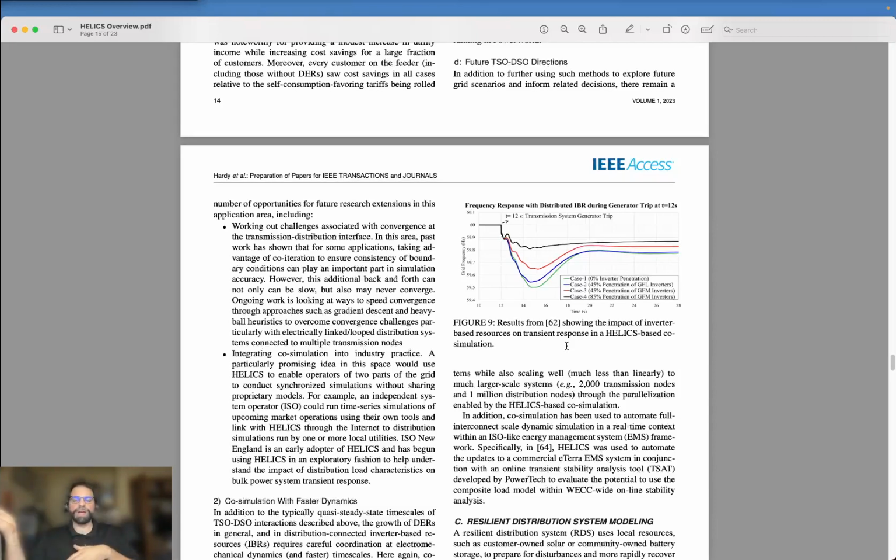So as some bulk power system event happened, a generator tripping or a line going off, classic kind of transient analysis things, the inverter models in GridLAB-D were set up to handle these very small timescale responses and to simulate how inverters might respond to that. And obviously, I shouldn't say obviously, the inverters were modeled as conforming to different standards. So grid following, grid forming, that kind of idea.